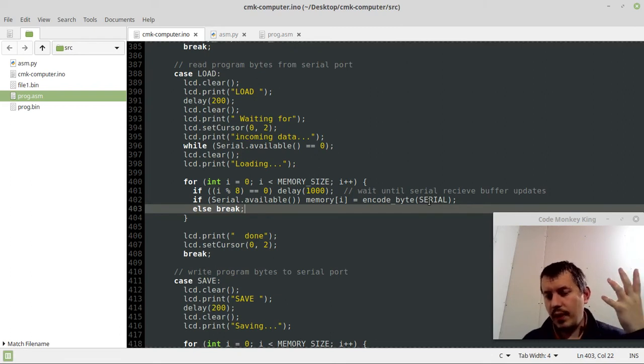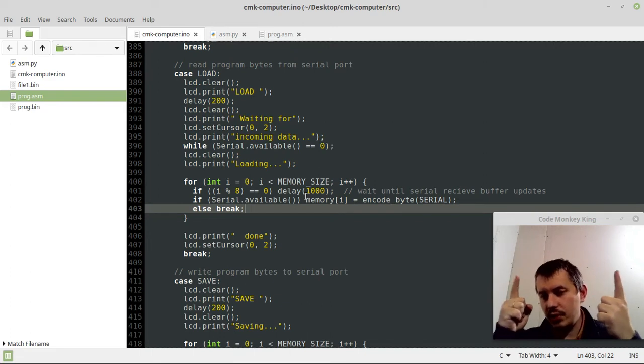Until I found one question somewhere, I don't even remember where exactly. But anyway, the idea is that we can make use of what is known as the baud rate, which is quite slow. The baud rate is the speed of how fast the characters are being sent via the serial port. And from the circuit level, we have a pin that transmits the signals, and another pin that receives the signal.